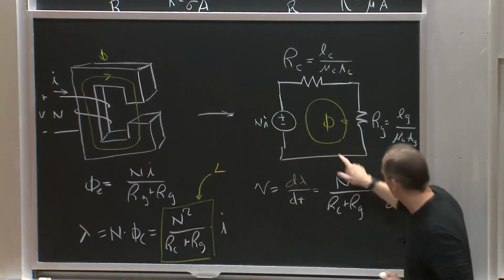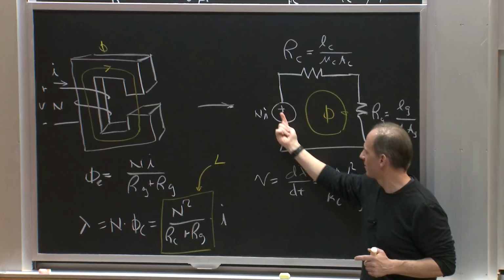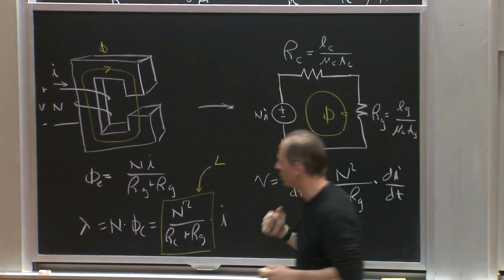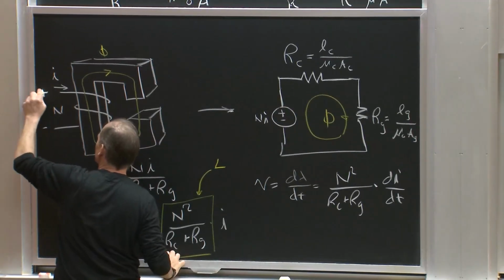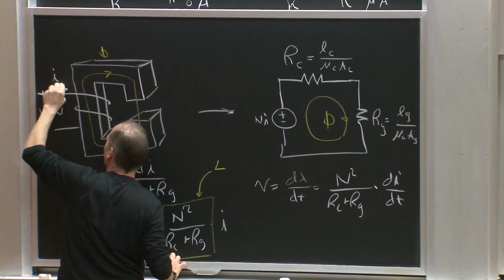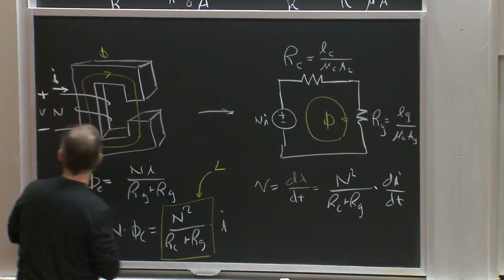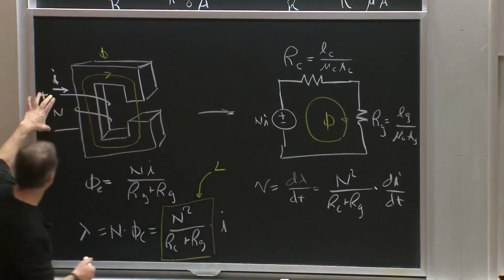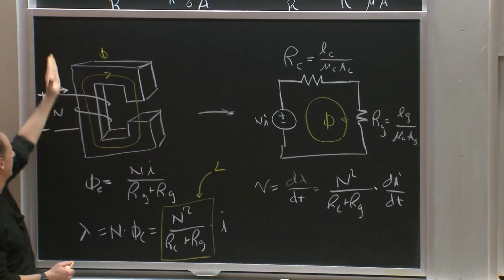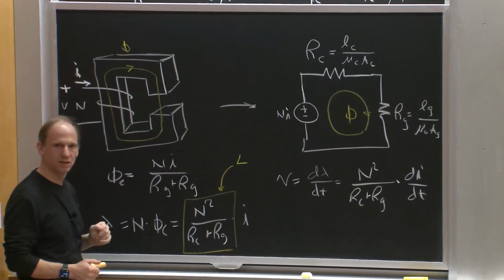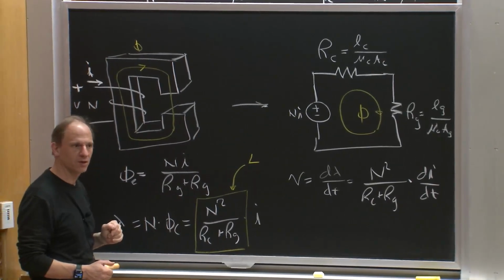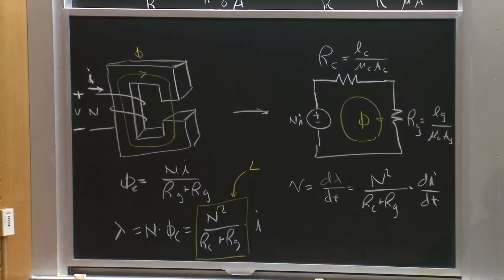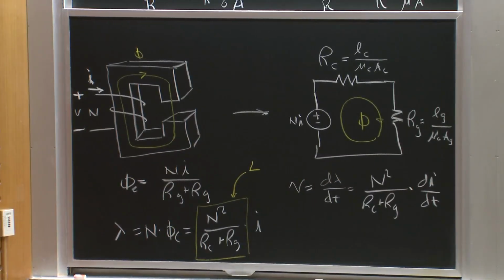If you notice, the flux I'm talking about is the flux coming out of the positive terminal of the MMF source in the magnetic circuit, and it relates to the voltage with the associated variables of the current going into that winding. So if I define a current and I get the MMF source, the flux coming out of the MMF source gives me the voltage with this polarity. So it's the V and I, and V times I is the power into the component. Any questions about that? So that's just a very quick review of last class.